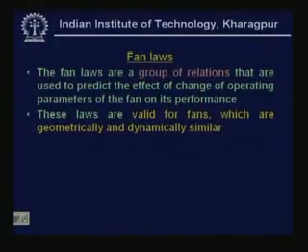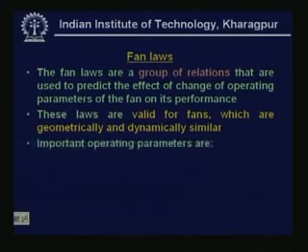However, you can use the fan laws to compare one forward curved blade fan with another forward curved blade fan of different size maybe. So, this is what is known as geometrical similarity. Similarly, you also have to have dynamic similarity, that means the force ratios for these two fans have got to be the same. So, for these geometrically and dynamically similar fans one can use the fan laws.